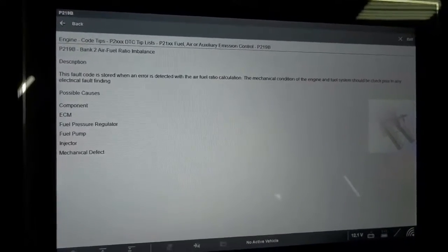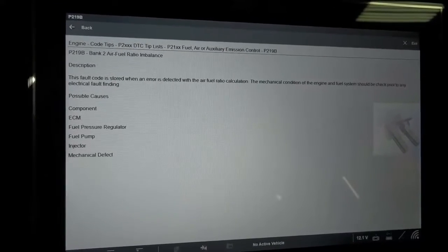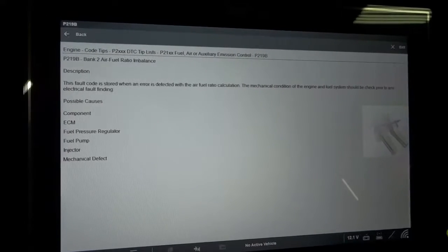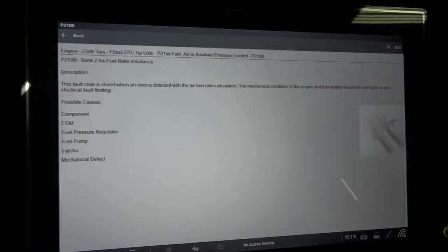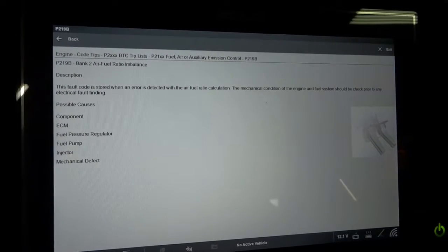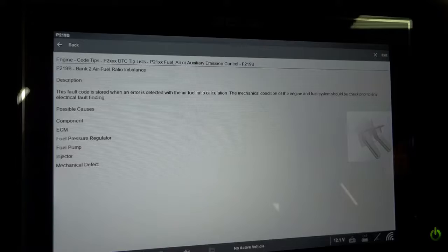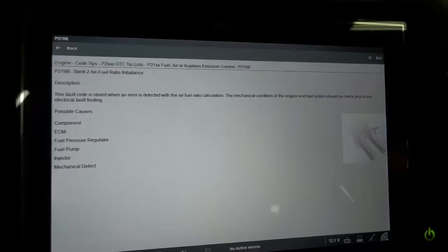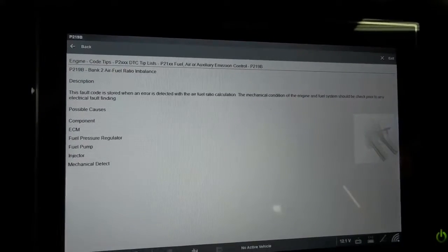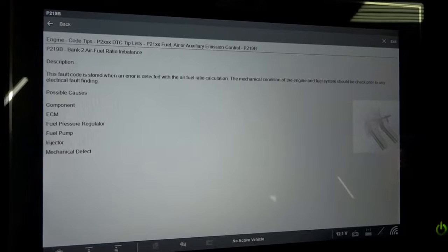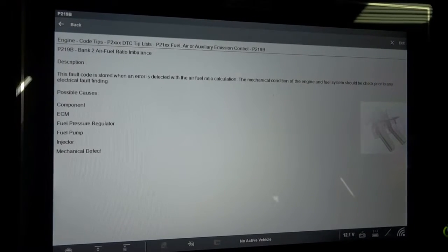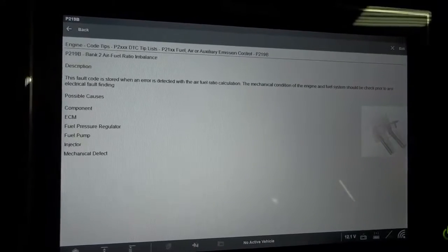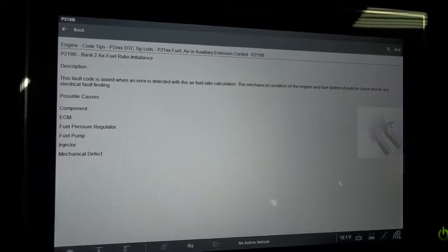These Hondas are known for having carbon on the fuel injectors, okay? Because this is a direct injection system. These injectors usually get covered with carbon on the tip of the injector, which basically affects the way the injector sprays fuel in the combustion chamber. We remember on the top repairs on the intelligent diagnostics side of the scan tool, the top repairs recommended replacing the fuel injectors. So now what I would like to do is test these injectors.